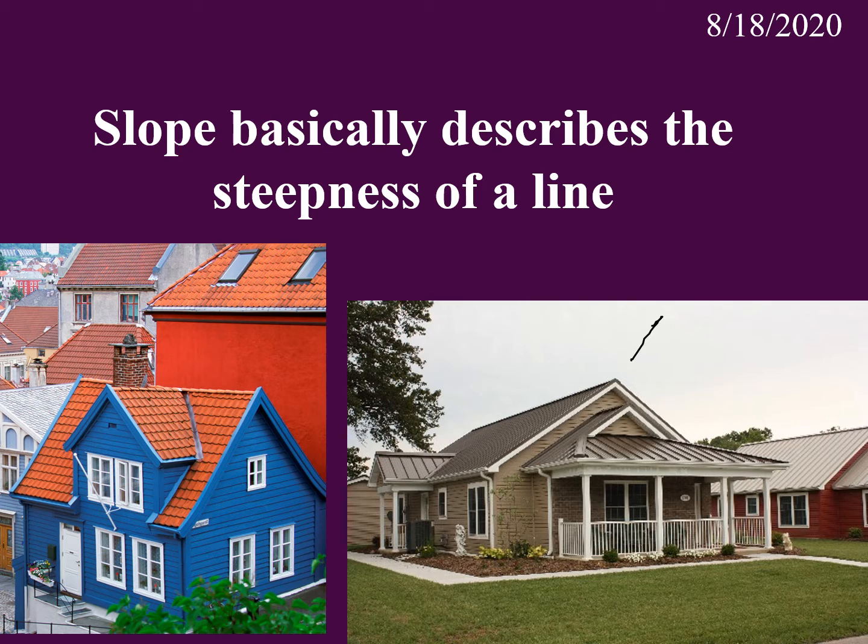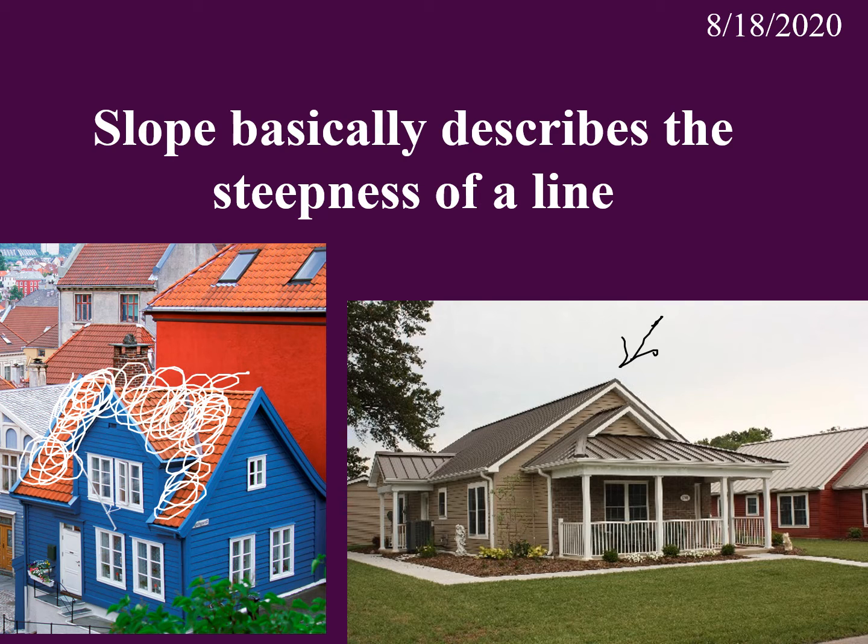Northern people can't have roofs like this. They have to have them a lot steeper. Why do you think that happens? Because of snow. Snow comes along and builds up on top of their roof. Boom, boom, boom, boom, boom. Snow is water, right? Water is heavy. The more snow that gets packed up there, the more it's pressing down on your plywood roof. You've got shingles, but underneath there is just a bunch of plywood.